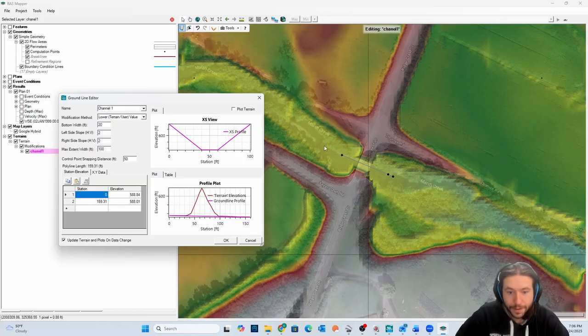We want to match, basically take our elevation from upstream of our bridge, run it to downstream of our bridge, and then it's cutting just a generic cross here, which isn't 100% realistic, but we're doing just a rough model, and it's going to be a lot better than damming up our flow from that bridge being in there. So we're going to edit our geometry a little bit here, and I'm just going to visually try and match the stream going through here.